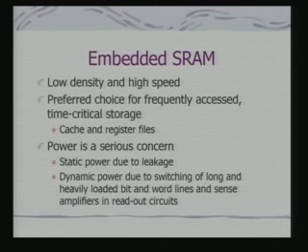Then there will be what we call dynamic power consumption, due to switching of long and heavily loaded bit and word lines, because these bit and word lines are connected from cell to cell. Obviously, I shall need current to drive these bit and word lines to provide me the correct data. So, there will be dynamic power consumption, that current will be driven into those lines when I am actually selecting or reading a word from the memory or writing a word into the memory.